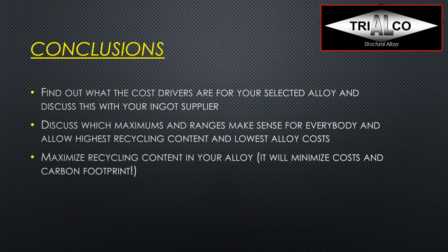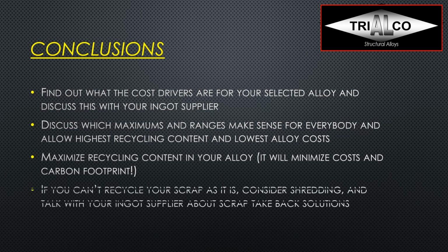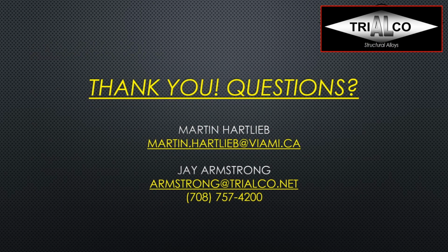Maximize recycling content in your alloy. It will minimize costs and carbon footprint as well. If you can't recycle your scrap internally as it is, consider shredding and talk with your ingot supplier about a scrap take-back solution. With this, we're coming to the end of this webinar.